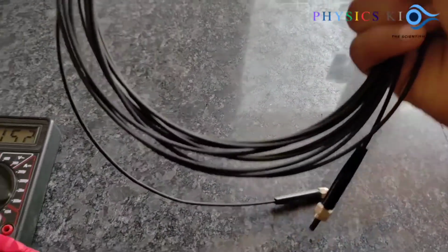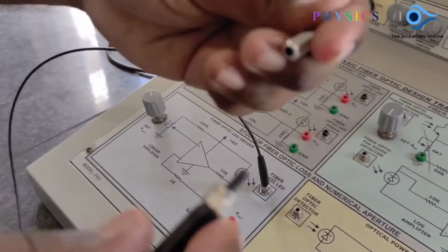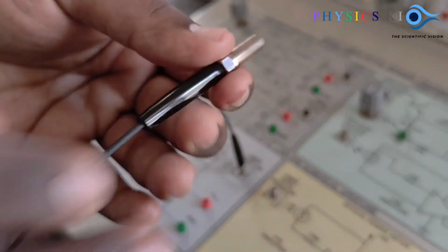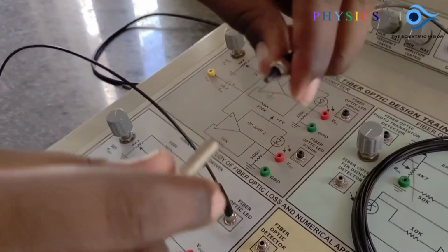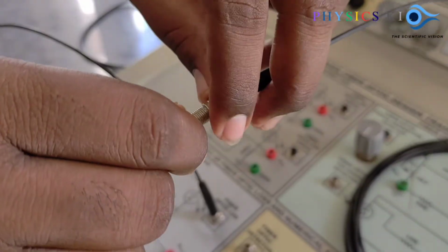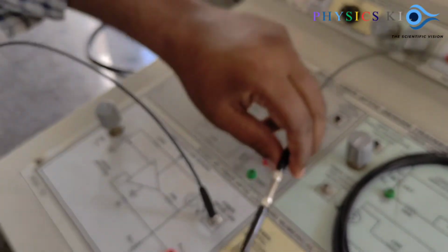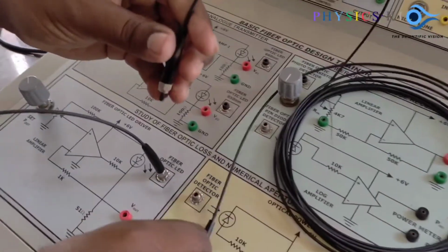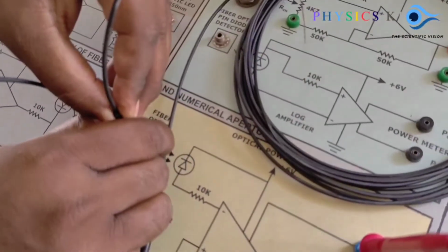Okay, now connect this 5 meter optical fiber cable using our coupler. So I am connecting the coupler here. Again it is a nut bolt type, so fix the coupler. Now on the second end of the coupler, fix the first end of the 5 meter optical fiber cable. Okay, and after that, light will pass through the 1 meter cable, and you can receive the light at the end of the 5 meter optical fiber cable.